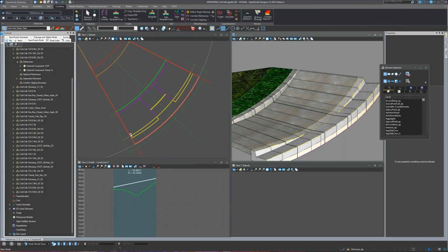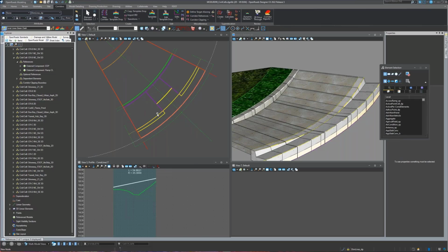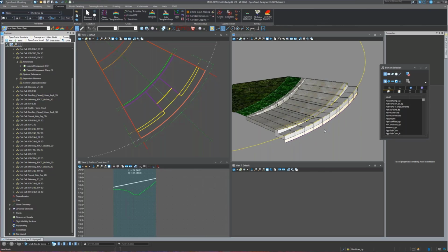My varying slope is here. So when I'm talking about this particular one, there may be situations where we've got to increase this distance from 7 to something a little bit higher to make sure that we've got a 1/12 that comes down here. So you can see this one's slightly different. It comes down here, but this one has a little header curb at the back.